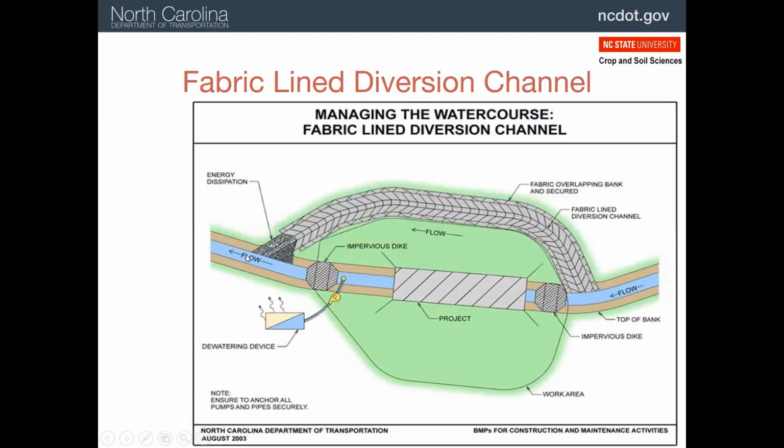Finally, another option, the fourth option, is to dig a ditch and just divert the flow into the ditch. So that's probably the most common. Now this ditch would have to be lined because we need to make sure that this water, as clean as it is, doesn't get dirty from our construction. So it's going to go into just like a clean water diversion. Put it into a plastic lined or geotextile lined ditch and back into the stream.